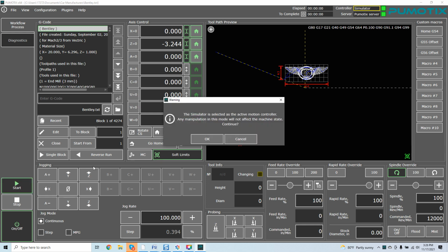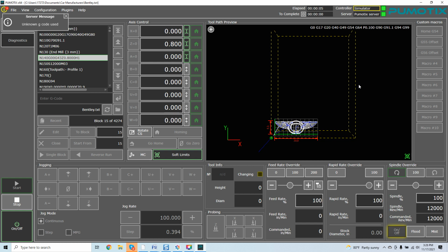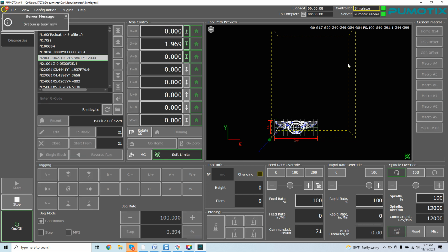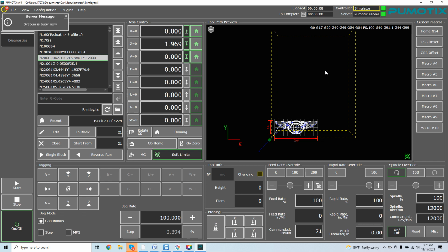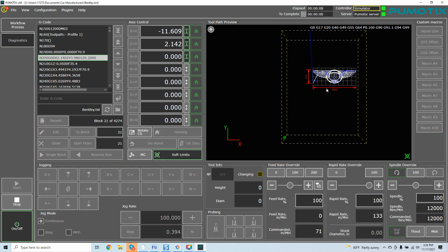As long as you hit cycle start, you get the simulator mode again warning. As I do that, you'll see she'll start and then she'll zoom back out. As soon as the spindle comes back down, you're back out, and you can see your soft limits are set. So again, very, very powerful. No switch implementation actually required. I'll hit go to 0. If I decided to mount this work in the actual G55 offset position, just click it, go to 0, and you're right over to it. So very, very powerful.